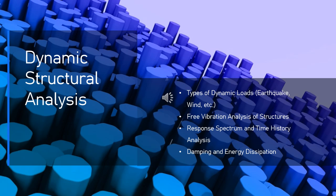Applications of response spectrum analysis. Seismic analysis. RSA is widely used in seismic engineering to evaluate how structures, such as buildings, bridges, and dams, respond to earthquakes. The seismic excitation is typically represented as a response spectrum derived from actual ground motion data or from a design spectrum based on seismic hazard analysis.